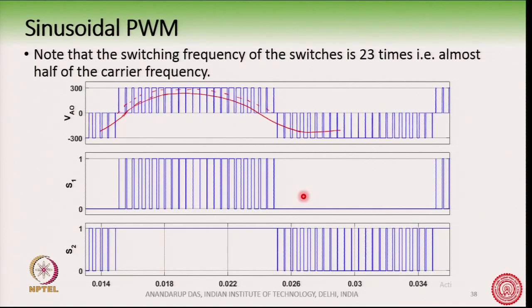This again will require that we have heat sinks of different types for S1 and S2, and subsequently also for S3 and S4, which is kind of challenging, right. So, for this operating condition, the outer switch S1 will have more losses as compared to the inner switch.